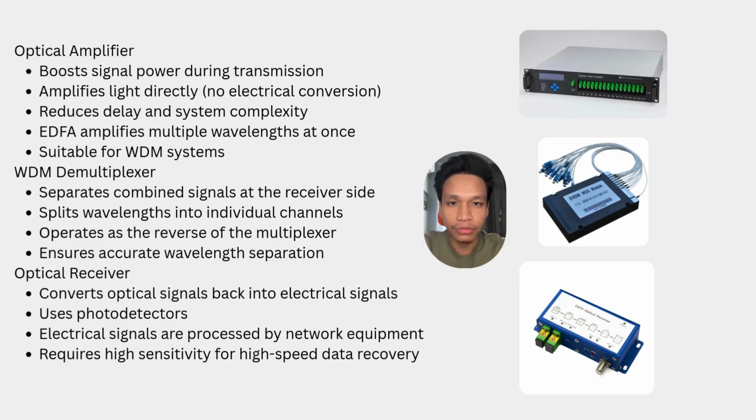Hi, my name is Muhammad Firdaus bin Nasaruddin, and right now I will continue on the slide of system component background. The next one is the optical amplifier, which boosts signal power during transmission and amplifies light directly, with no electrical conversion. It can reduce delay and system complexity, and an EDFA amplifies multiple wavelengths at once.